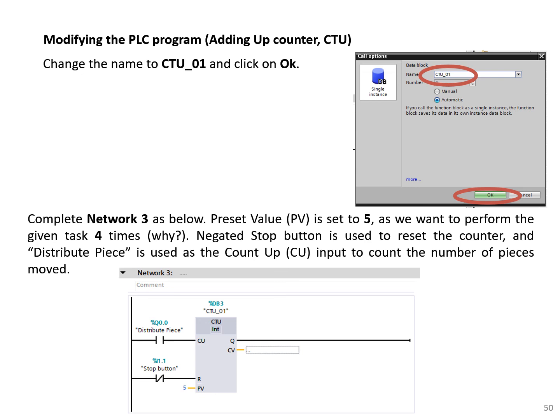This is the distribute piece. So what is that distribute piece? This is the piston underneath of the magazine in the distribution station. Every time that distribute piece actuator moves forward, we have a piece provided for the swivel. So that swivel will come and will pick the part.